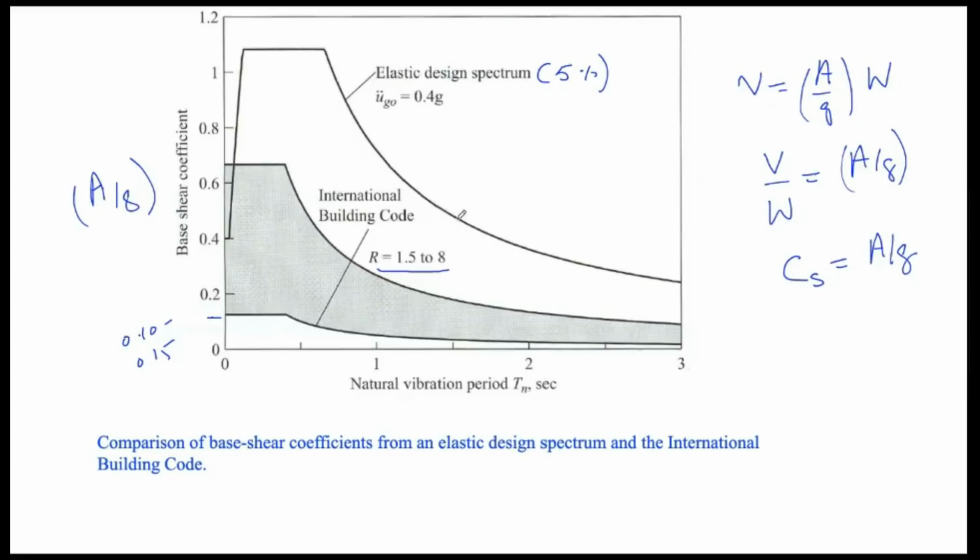For example, if you are doing shake table testing for structures, when you input that accelerogram to the test model, you will see that the model will get damaged, because the resistance or the base shear coefficient is much less than the demand for an elastic system. So the challenge to the engineer is to design the structure so that the damage is controlled to an acceptable degree. As an engineer, our job is not to avoid damage. It will happen, but the challenge is to bring it to an acceptable value.